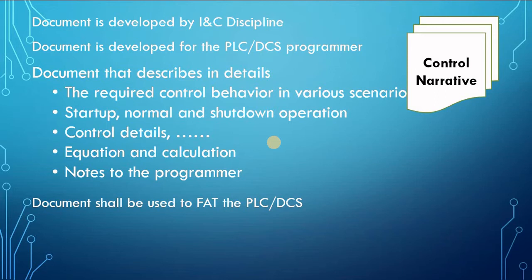calculation tables, and so on. Now, one other thing is that if you work in a big company, you may have a specific document which explains the HMI: your lines, colors for different fluids, valve colors, what the messages are, how to display the messages, and so on. But if you have a small company, you may not have all these things.